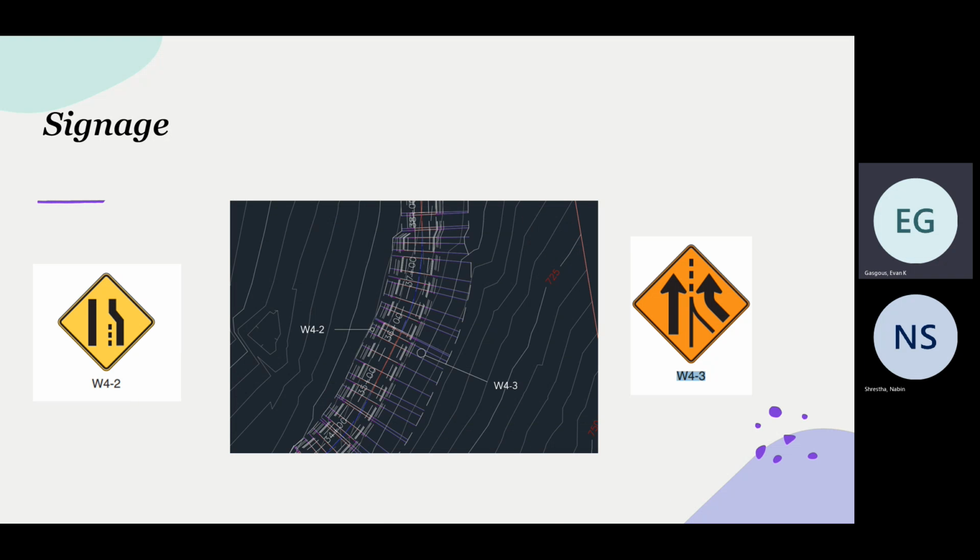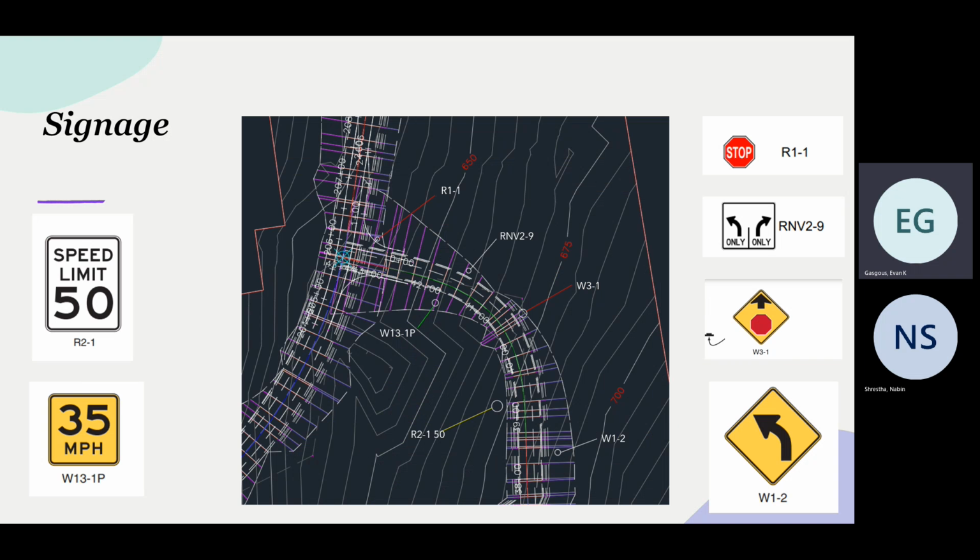Secondly, we're going to have the second transition point. We have a merging and increasing of lanes. And next is the transition to the intersection, which is 2 lanes on the right side, 1 lane on the left side. And at the turning point, we have a 30 miles per hour speed. We have left and right turns with a stop sign, and we have a stop sign warning 250 to 350 feet from that.